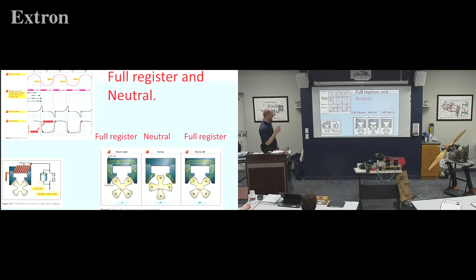So what happens is we have our contacts closed, we're rotating that magnet, the lines of flux are changing, and just after that neutral position, we open the contacts. So at neutral, we have the highest change, which means we induced the highest amp draw. And when we say amp draw, we're literally, with our generator, with the coil, dumping power from ground through the coil back to ground.